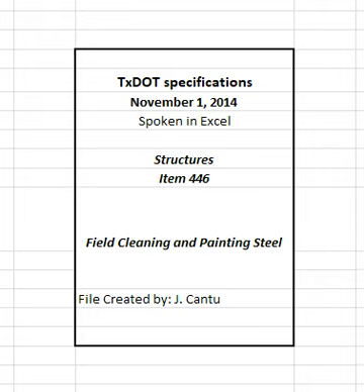If, in the opinion of the engineer, there is an objectionable amount of dust in the atmosphere, discontinue painting or take necessary precautions to prevent dust and dirt from coming in contact with freshly painted surfaces or with surfaces before the paint is applied. Provide full coverage of the steel with the concrete surface when painting steel that is in contact with concrete. Do not extend the paint more than 4 inches onto the concrete surfaces or as directed. Ensure when painting is complete the only visible paint on concrete surfaces is the finish coat. Remove excessive or objectionable paint on concrete surfaces in an approved manner.